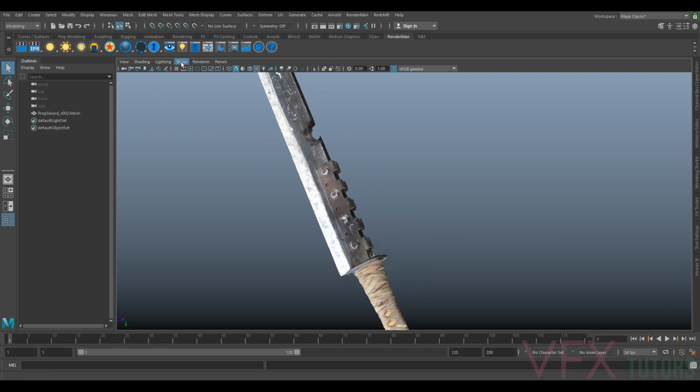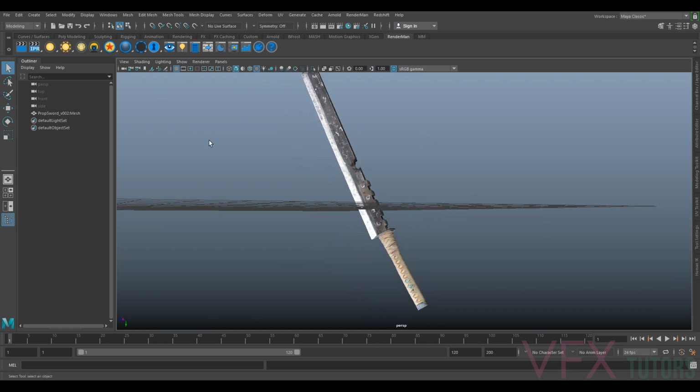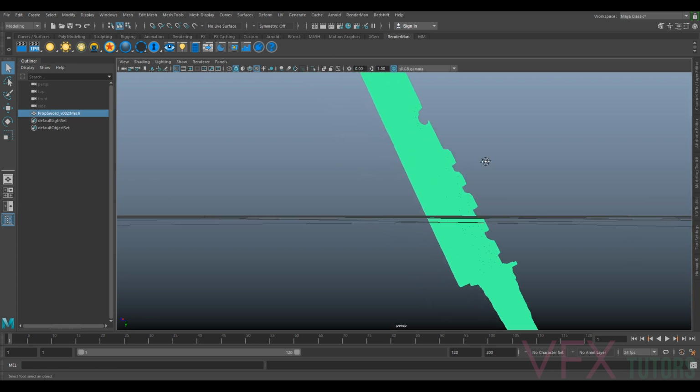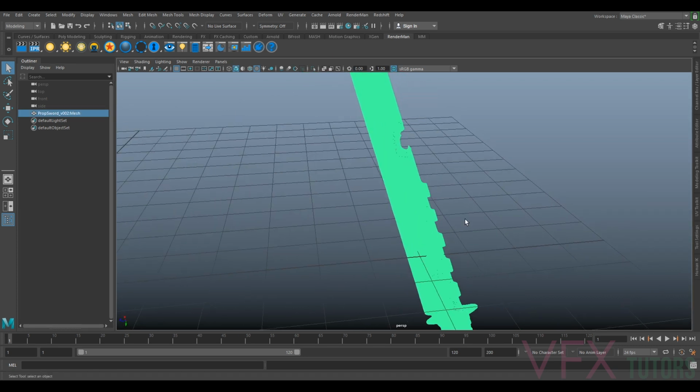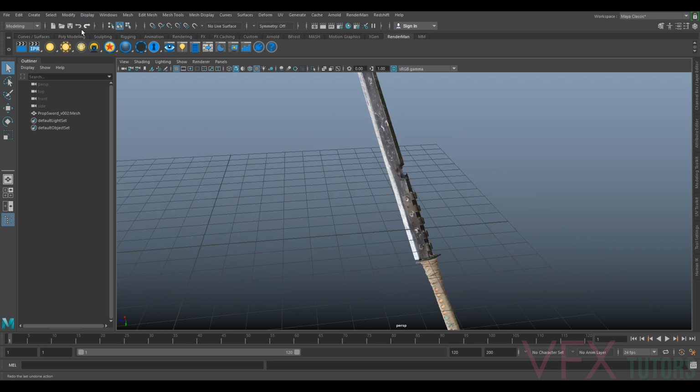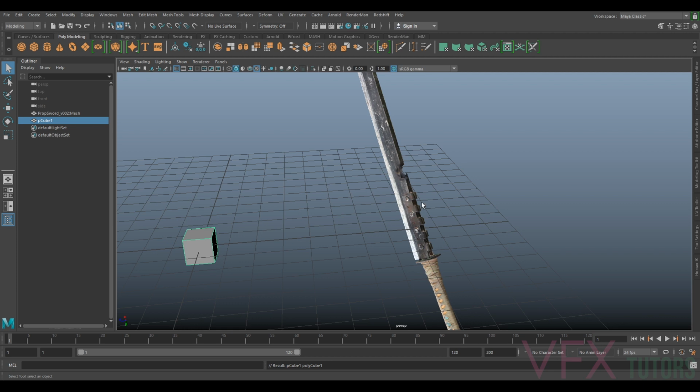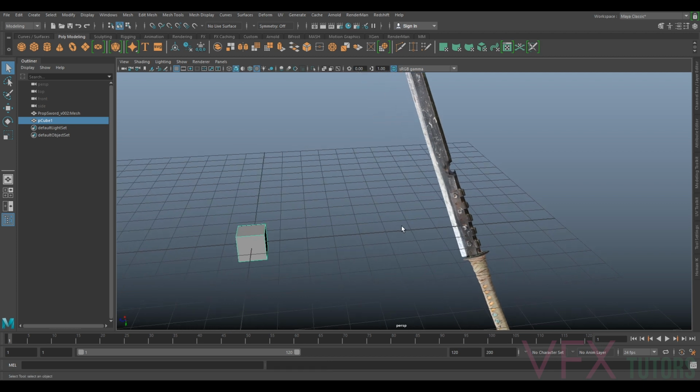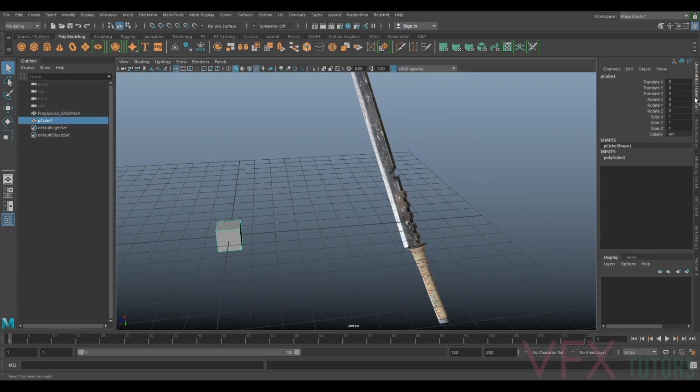So our first thing that we need to do is orientate and scale. If you did the previous tutorial of the set build, we're going to do something very similar. I'm actually going to start with a cube because it's just easier. And I'm just going to go to my channel box layer. I'm going to make sure I'm on frame 1, because what I need to do is keep this position, but this position is not great to do any modeling in. We want it at the origin.